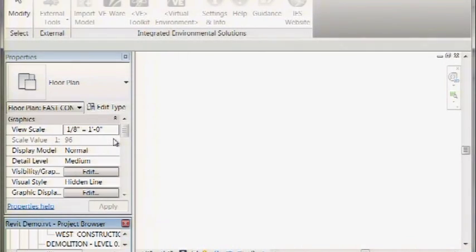But often what you'll see is that if one of these rooms is causing me a problem, what I'll do is just go in and say, that room, I'm deleting it. And often when you run this model check, you'll see that it's all the rooms surrounding it that have errors, because when you have an intersection error, the intersection error is the room itself and the room adjacent. So if you actually go through and print out the floor plan and check it, you'll see it's all the rooms around it and then that room. So you'll realize it is only one room that may be causing a problem. So that's one way to start to query if it's those pieces of your model or not.